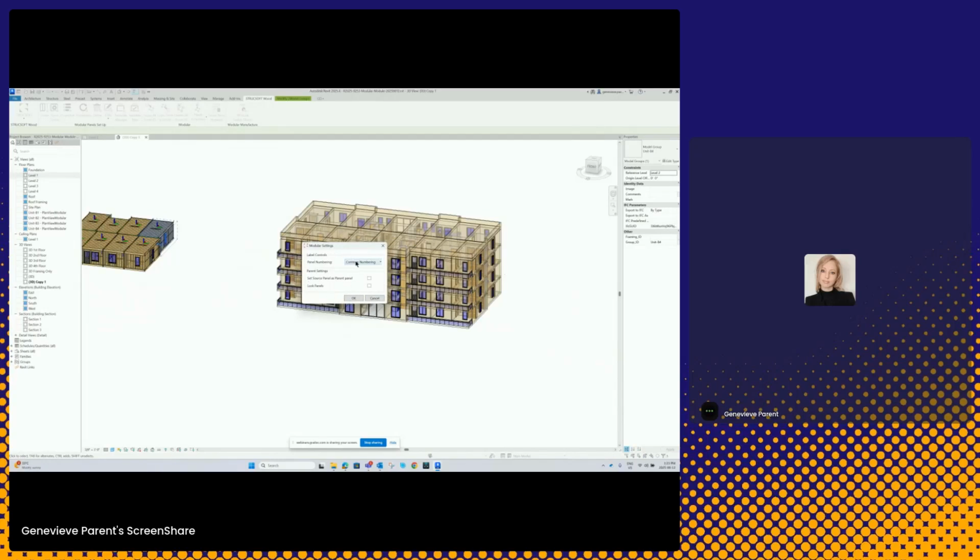Now, you do have different options. I know they were possibly covered in the last webinar, but we want to keep it simple. We're going to set source panel as parent panel. So this is going to be set as our parent panel, and we are just going to simply continue the panel numbering. Now, we could keep it the same as the original, so you do have both options available. And you do have the option to lock your panels. We're going to just keep this one unlocked though. I'm going to hit OK.